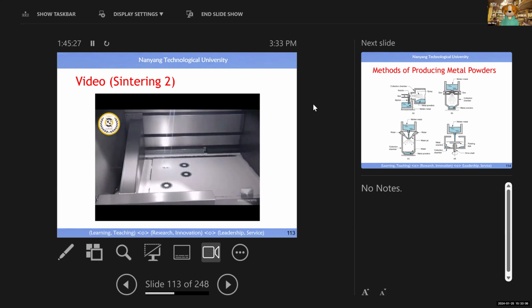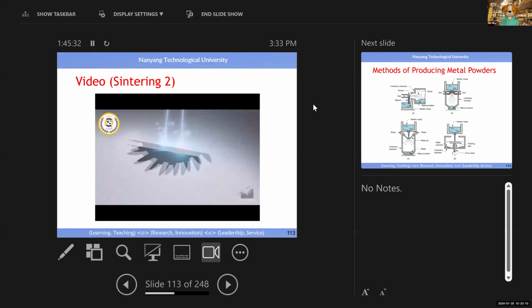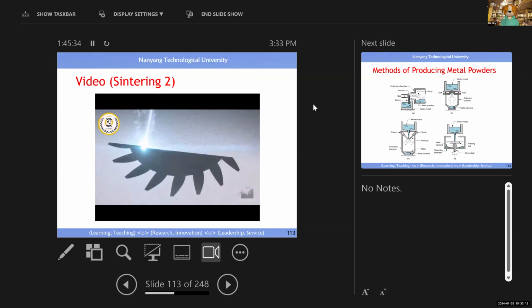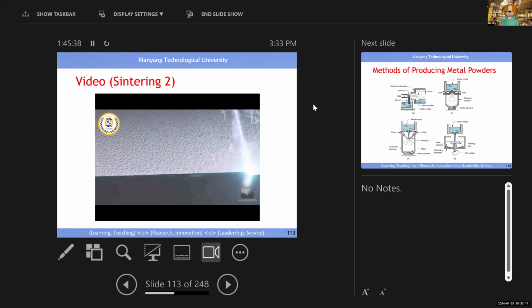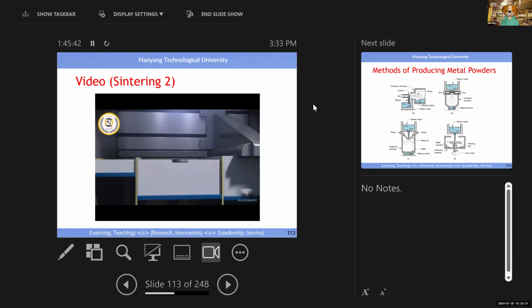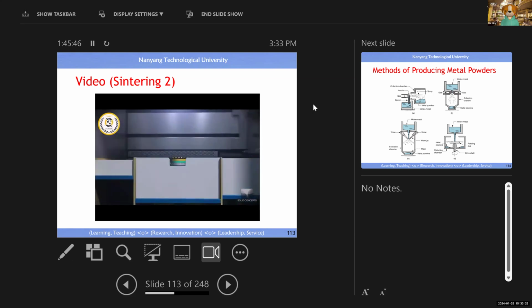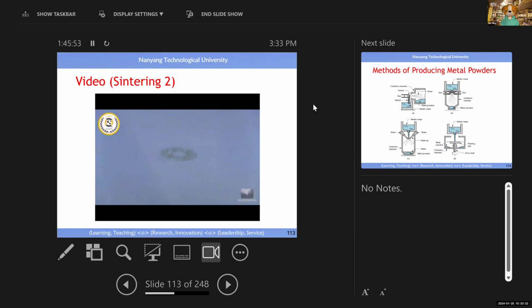Then let's use the laser. Solidify the liquid. So this looks like this. Once the layer is completed, the base plate is lowered. So let's say you see the powder go down layer by layer. Right? The DMLS machine builds layer on layer.